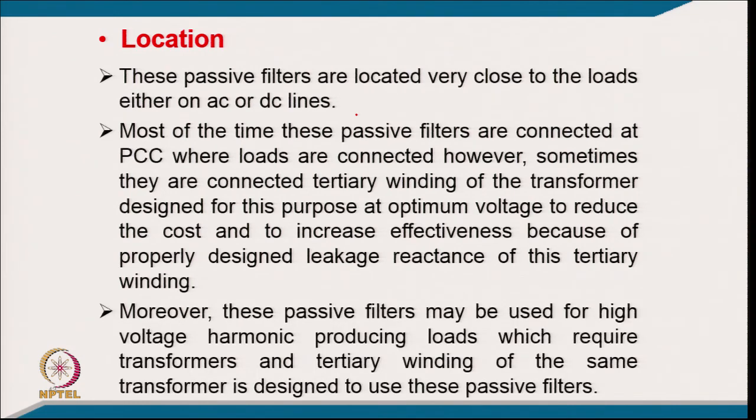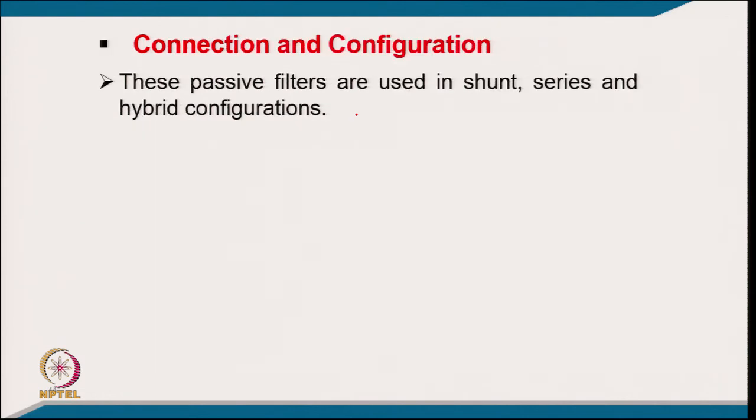Moreover, these passive filters may be used for high voltage harmonic producing loads which require transformers, and the tertiary winding of the same transformer is designed to use these passive filters.